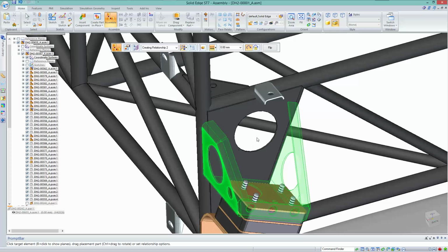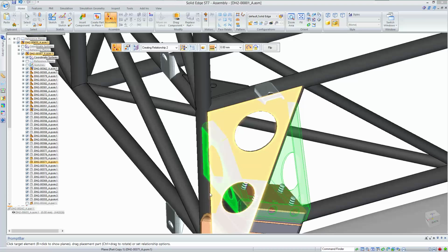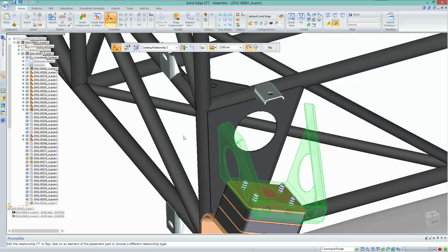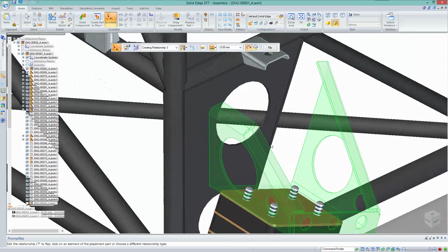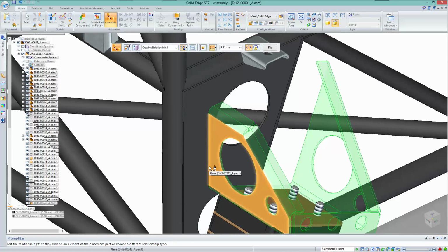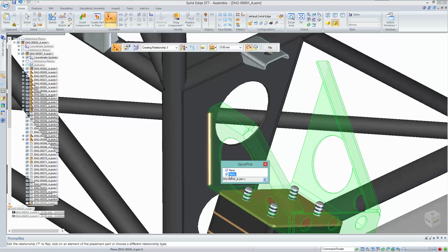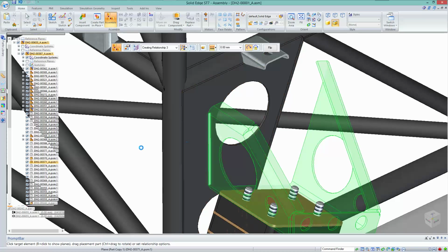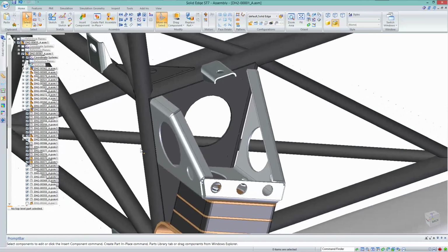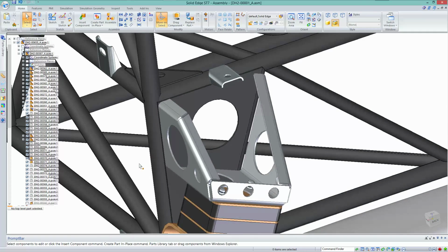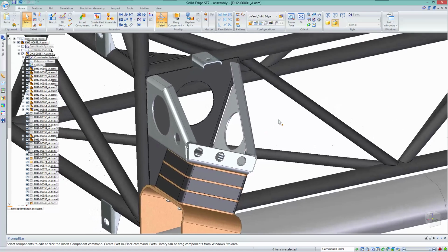So that particular part, well, I wasn't able to select that face a second ago. Wrong face, we'll use Quick Pick perhaps. I've loaded the information about that part file into memory, so initially it wasn't selectable because Solid Edge hadn't done that, so that's why I was able to load up the assembly a little bit quicker than I perhaps would normally. And finally we're going to seat the thickness face onto that plate that's already in the superstructure for the helicopter.